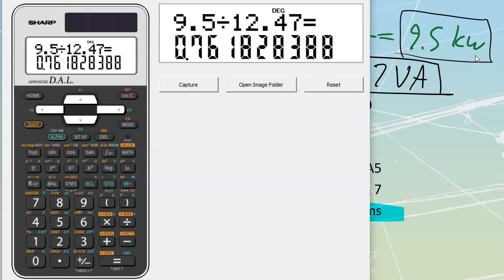There's another one in there. I'm not going to go through it. You can go through that one because it's a little bit more tricky and it deals with a phase value of voltage, which means you're going to have to do some conversions to either go to the line values or do everything as phase values, voltage in the phase, current in the phase, and then multiply it by 3 instead of root 3. Either one of those is going to work.